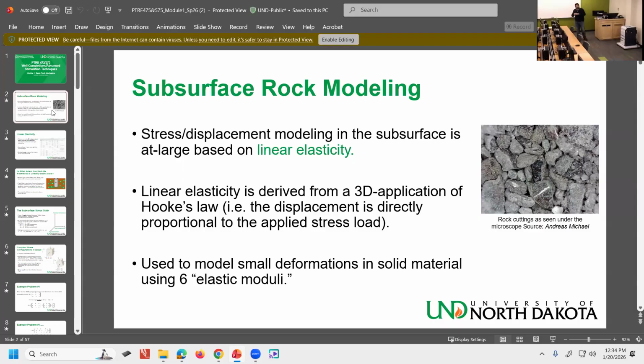So if the material is 1 meter long, and then I apply a stress of X PSI, and I extend it to 110 centimeters, so it's 1.1 meter, the strain would be 1.1 minus 1 divided by 1, so it would be 0.1. Okay, dimensionless. That's one way, but that's the most simple example, okay? Hooke's law, basically.